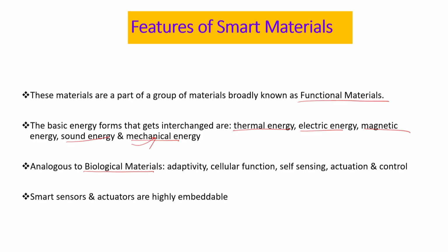The actuation part we will talk about later on. So, these are some of the good parts, and also you can embed such a system on another system. So, let us say I have an aircraft wing. The advantage here is that I can have a lot of these smart sensors embedded inside the aircraft wing, and since each one of these sensors can convert mechanical energy to electrical energy, that means at different points you can measure the change in the mechanical system, like what is the stress that is developing, the change of the stress dynamically you can measure, convert it into electrical